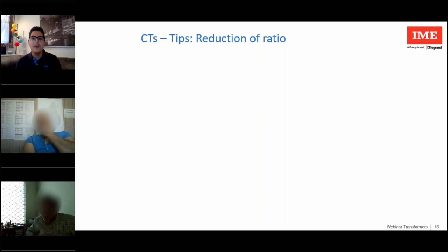What does this mean? If I choose a current transformer, for example, 300 to 5 amps, and the real current is 10 amps, for class 0.5 or class 1 the class starts from 5%, therefore 15 amps. The current transformer will be working out of class, giving a strong angle error that is reported on power values, and consequently on the measured energy. Unfortunately, I have seen many installations in this condition, and where it's possible, we can take advantage of this trick.